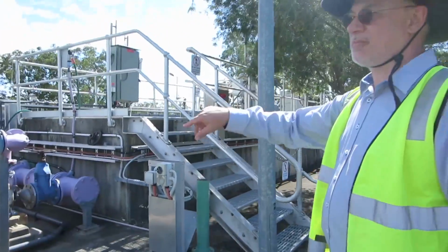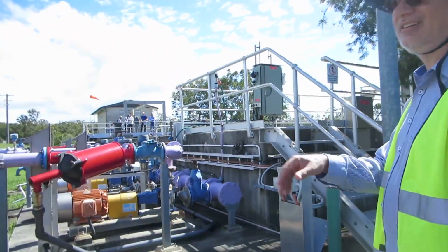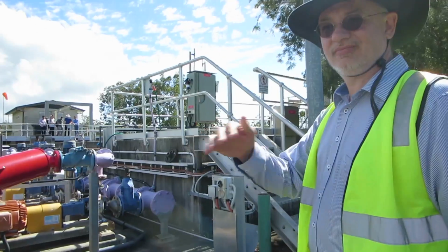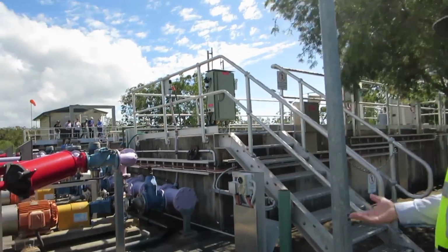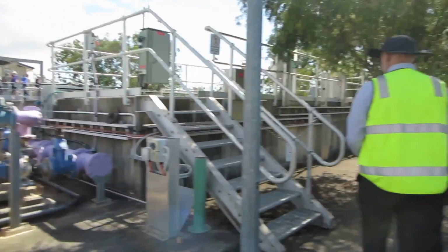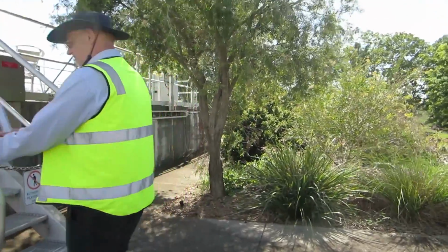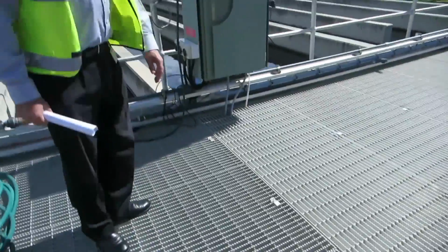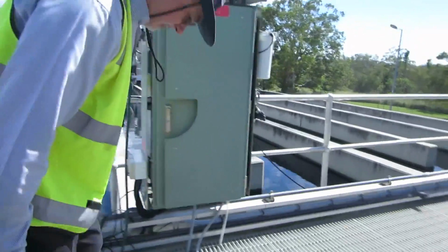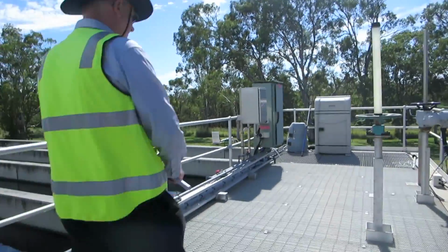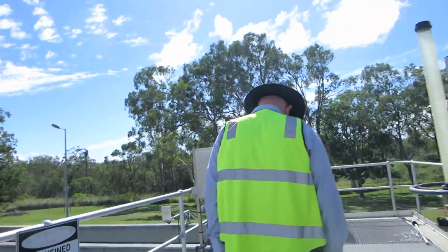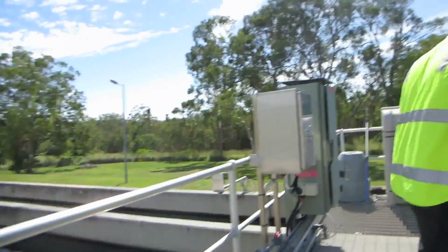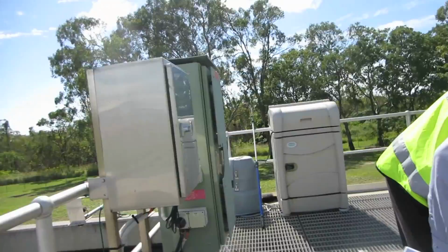The outlet stage is placed immediately after the dechlorination stage. In this stage, the effluent, which has a maximum chlorine concentration of 0.01 mg per liter, is pumped out of the plant in two different streams. 70% of the effluent is released to the freshwater stream in Hilliard's Creek, 2 km downstream from the plant. The other 30% is pumped out to a lagoon, and then it is used for spray irrigation of 68 hectares